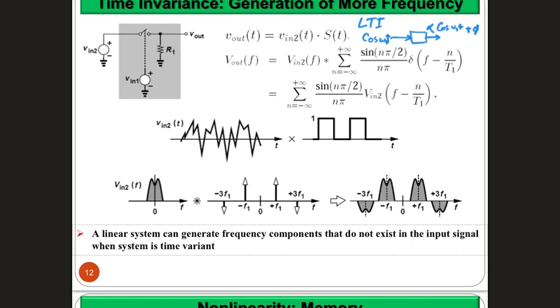Okay. Now, if you want to look at what happens in terms of frequency components, the best way to do that is to look at everything from the frequency domain perspective. If you go to the frequency domain, this relation, which is multiplication in time, becomes convolution in frequency. The first signal, which is Vn1, the input to this system, you just need to take its Fourier transform. An arbitrary signal would look in time domain this way. When you take its frequency domain representation, or the Fourier transform, it looks this way. Just some signal that has this frequency domain look and this time domain look, okay?